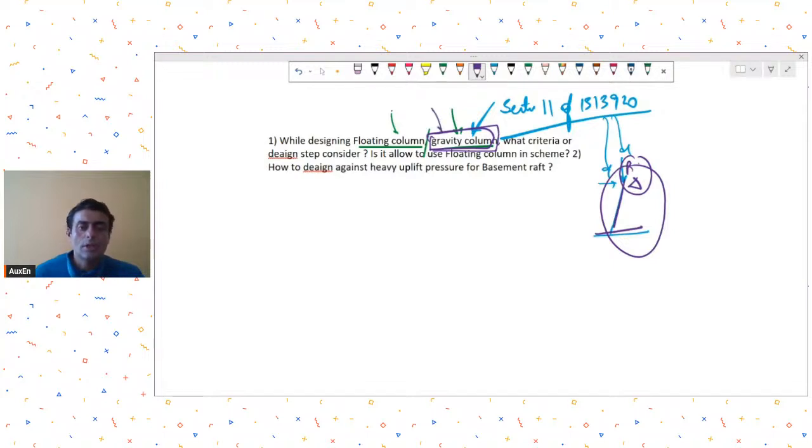So ensuring that is a bigger thing than designing the gravity column itself. Designing gravity columns, you have to just consider this additional moment that your columns may be subjected to, P times delta times the axial load. Okay, so design your columns for this additional moment, but in the model to ensure that columns are not taking any effects of lateral loads is a bigger challenge.